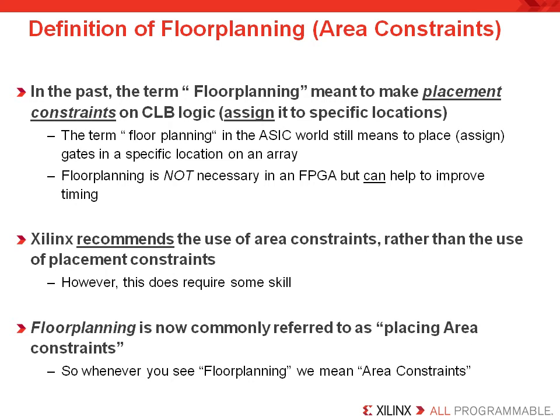Xilinx does not discourage the use of area constraints. However, this does require some skill. The trick here for engineers is to first floor plan the timing critical logic hierarchy to a region on the device. This can be done after some chip and design analysis. This brings a certain level of repeatability to subsequent place and route runs even if the netlist changes. Sometimes it can be a good idea to floor plan some non-timing critical logic to get it out of the way of the timing critical logic.